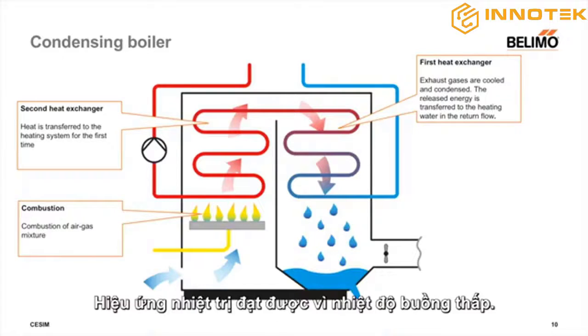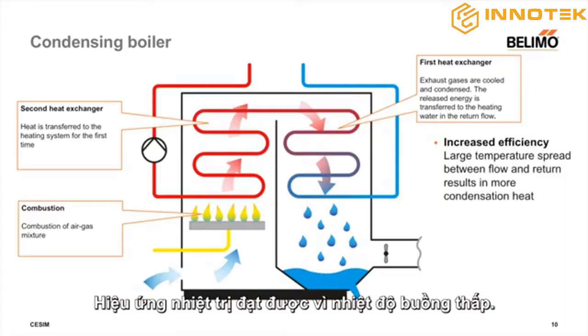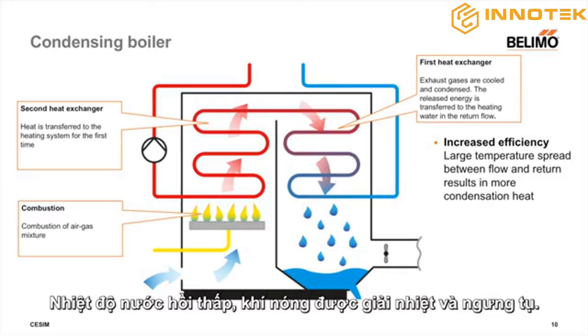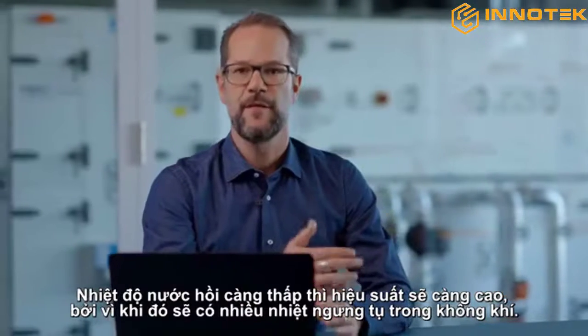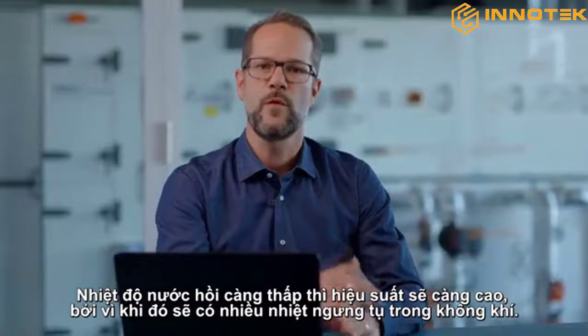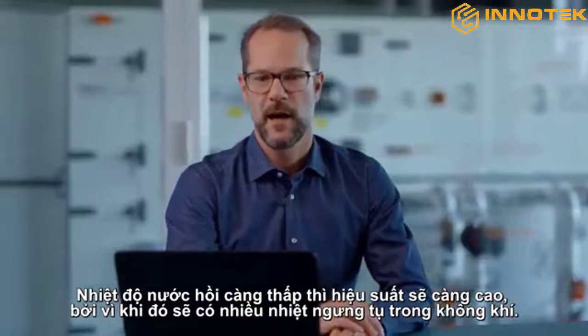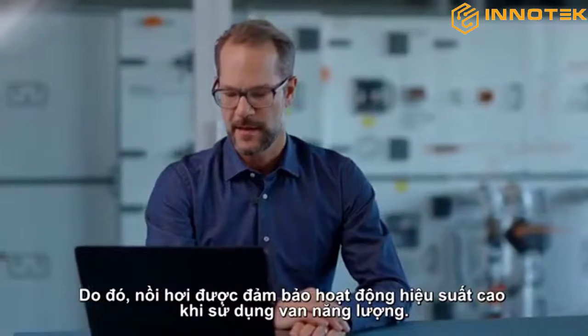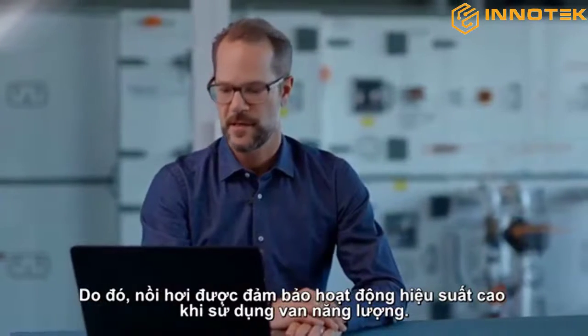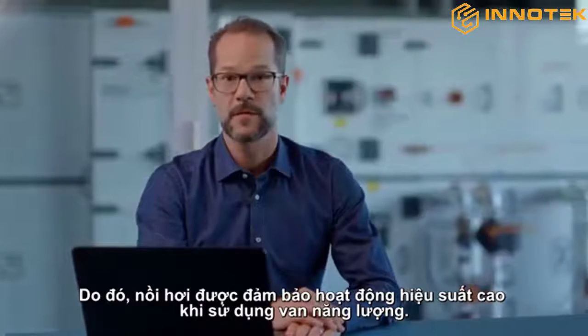The calorific value effect is achieved by low system temperatures. Due to the low return temperature, the gas are cooled and condensed. The lower the return temperature is, the better the efficiency, because I have more condensation heat in the gas. So therefore, the energy valve can ensure that this efficiency is guaranteed for condensing boilers.